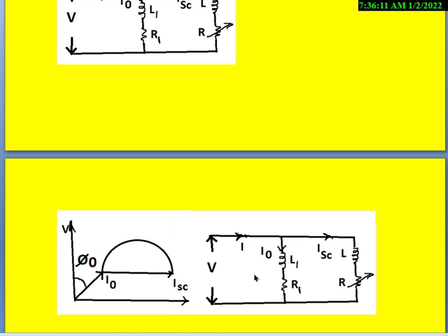And if you look at this, the second branch is nothing but the blocked rotor current, which varies with the resistance of the rotor circuit, but there is a fixed element called the inductance. When this R is equal to 0, the impedance of the circuit will become purely inductive in nature.